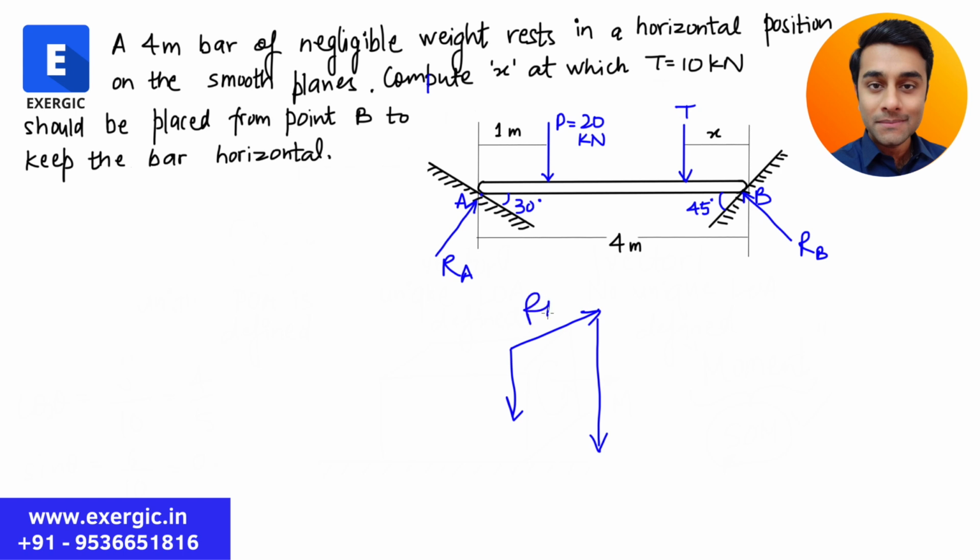This is going to be RA, this is going to be RB. Again, look, cycle in the same loop, in the same loop, in the same loop, again it is opposing, right? So a four-sided polygon you cannot make for such a body. Then how is it possible that a body in static equilibrium has four forces acting, but you are still not able to make a polygon with four sides?